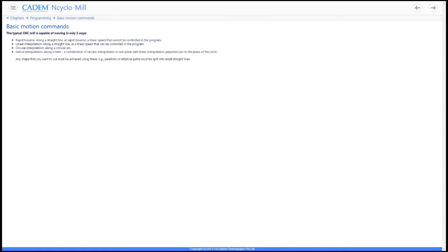The tool on a CNC machining center is only capable of these 4 motions. The program commands for these motions are G00, G01, etc. In addition, you have commands for changing the tool, specifying the spindle speed, starting and stopping the spindle, controlling the coolant, etc. Knowing just these and a few other commands, you can actually write programs for cutting complex parts.